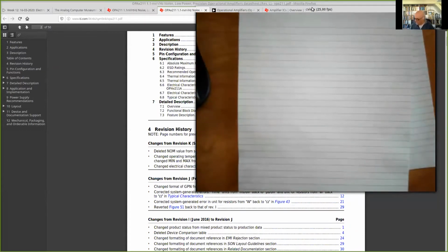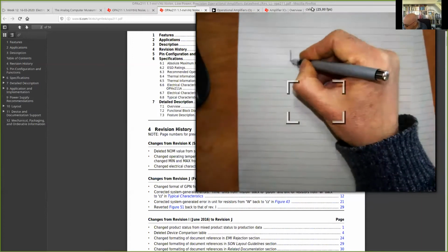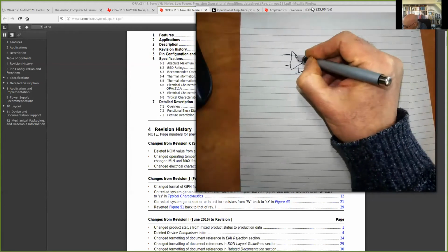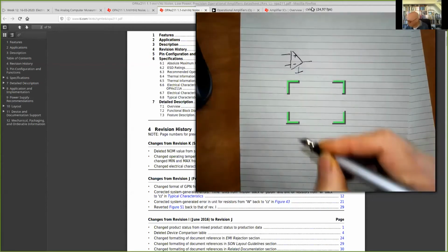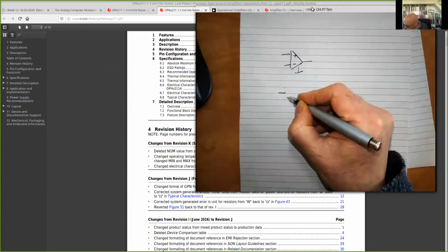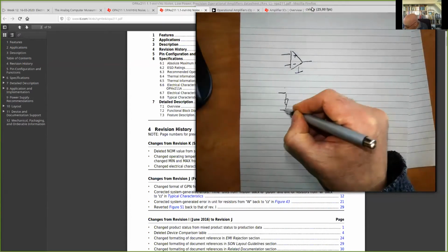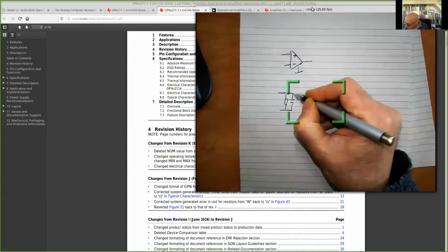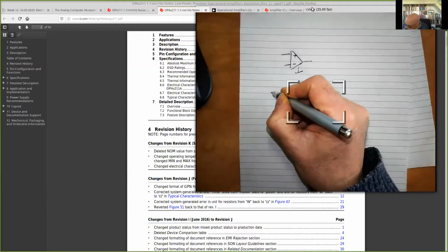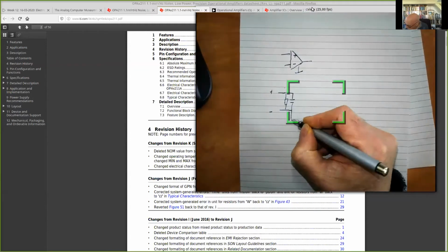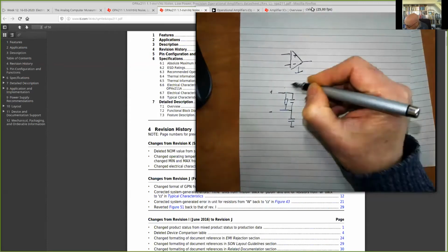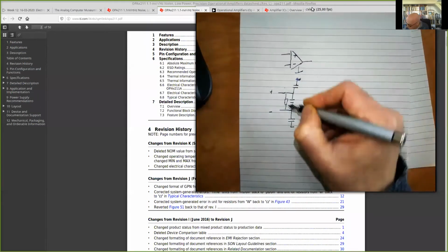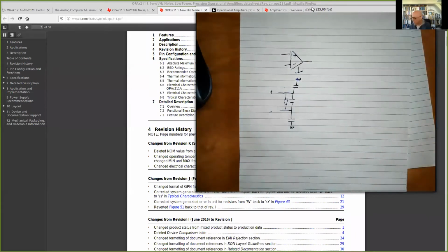So what we want is to make a small signal equivalent model of this thing, and that will consist of something like an input impedance. Usually it's a resistance and a capacitance. Common mode impedances, so let's do this plus and minus input. Common mode is usually modeled by a capacitor going to the ground node. And the ground node is the same as the one of the output nodes in this case.